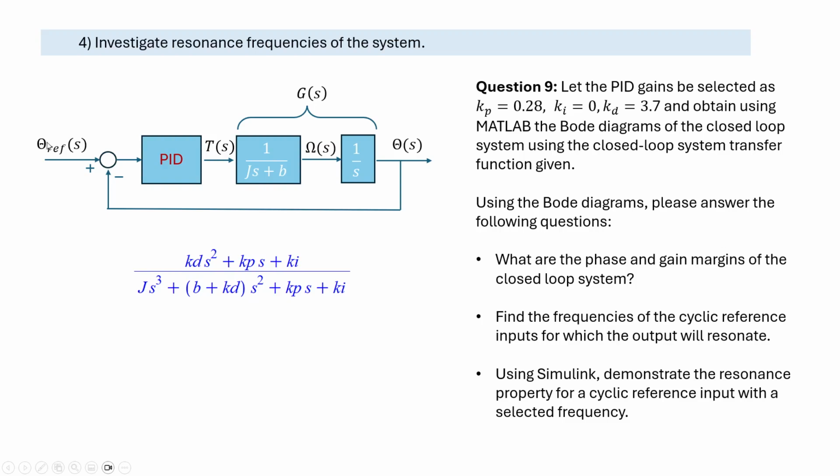It may end up being cyclic, or at least it must be studied for cyclic inputs, because sometimes oscillations may also arise in the feedback line due to, for example, noise and other reasons, and that oscillation may propagate around the loop. For that reason, it is really important to understand how the commanded angle oscillations could potentially put the output angle theta into resonance.